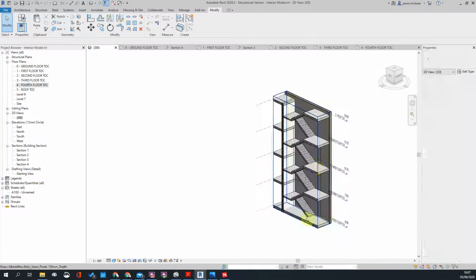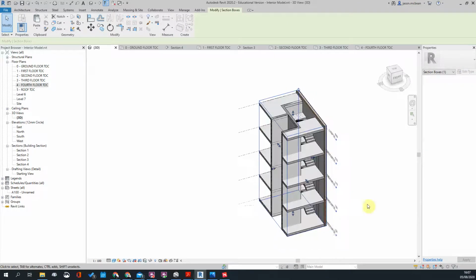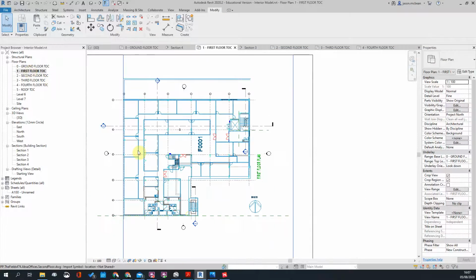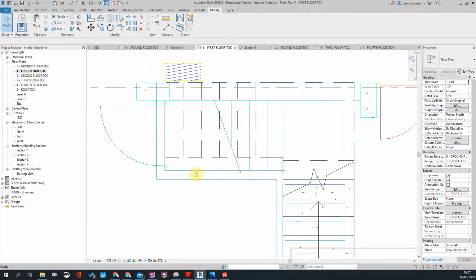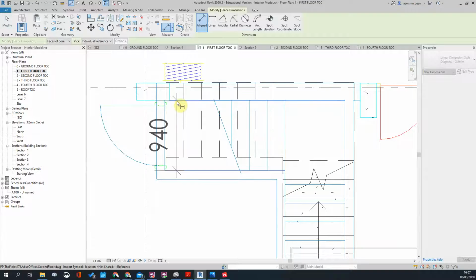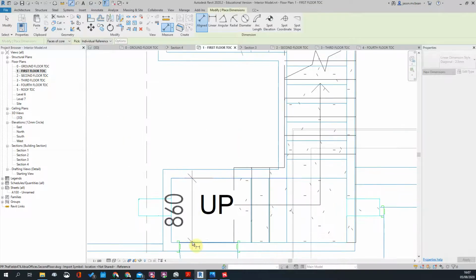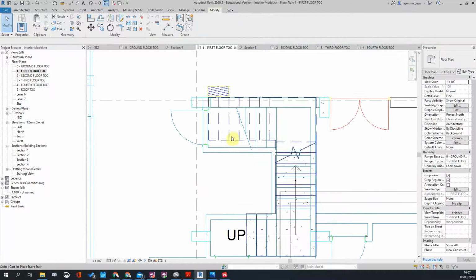Anyway, we've got some stairs. We'll fine tune the steps a bit later. In essence, I'm happy with the way that works. Now, the slightly concerning problem I have with these steps is that they're very narrow. Generally, you don't want to go too narrow on steps. 940. They're different sizes. That cannot be allowed. That's not right, so I'm going to make this whole thing 900.